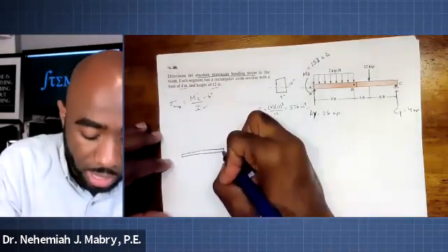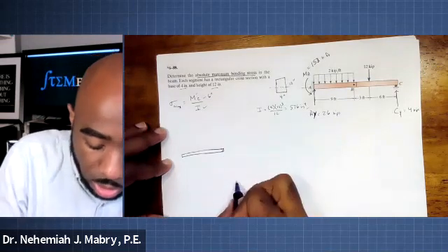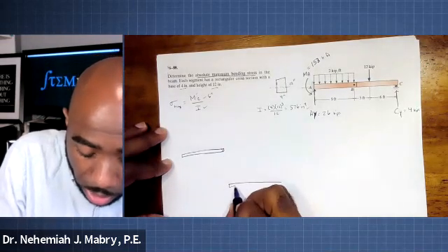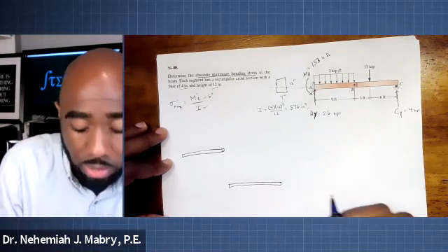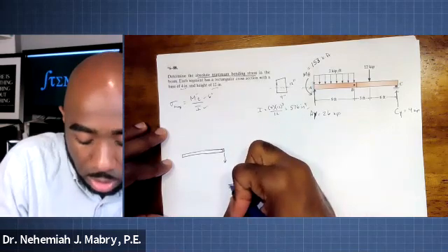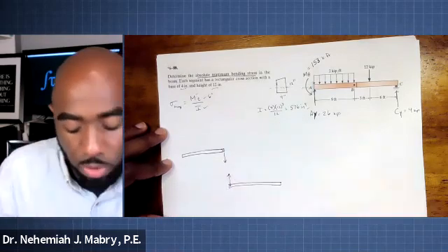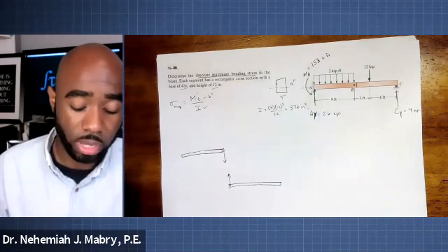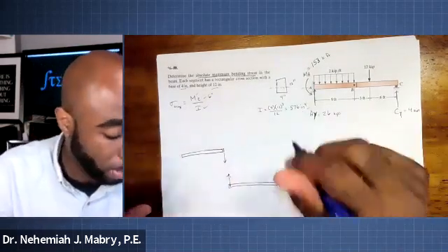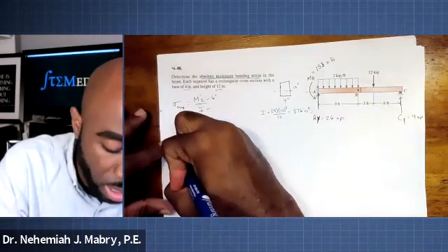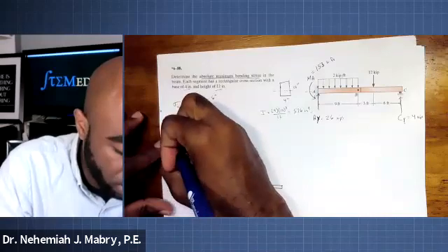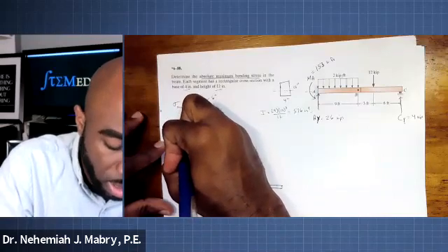Let's draw the other one right here. Imagine this is the left side and that's the right side. At the hinge, you're going to have a vertical force that's counteracted by another vertical force where the hinge is located, but you're going to analyze these separately. So we know here there is a moment of 153 kip foot.